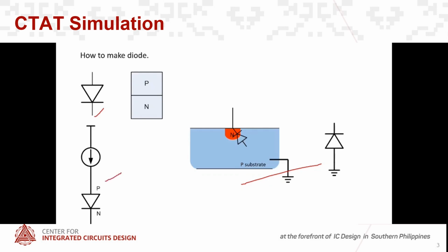Our target configuration, or what we wanted, is that the anode of the diode is free to be connected anywhere, not to the ground, but here the anode must be connected to the current source. But in this configuration, as you can see, our anode is connected to the ground. So this is not the case that we wanted. So we look for another configuration that would fit our diode, which we need for the CMOS process, so it can be implemented in CMOS.